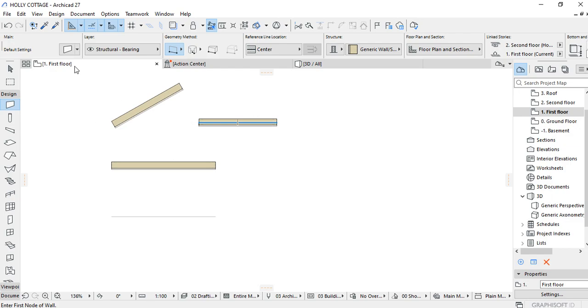Here on the ribbon, the tracker is controlled here. So if we hide the tracker and come to model our walls, now we cannot input measurements according to the tracker because it is hidden. So we should ensure to always have our tracker on to be able to aid us in modeling.